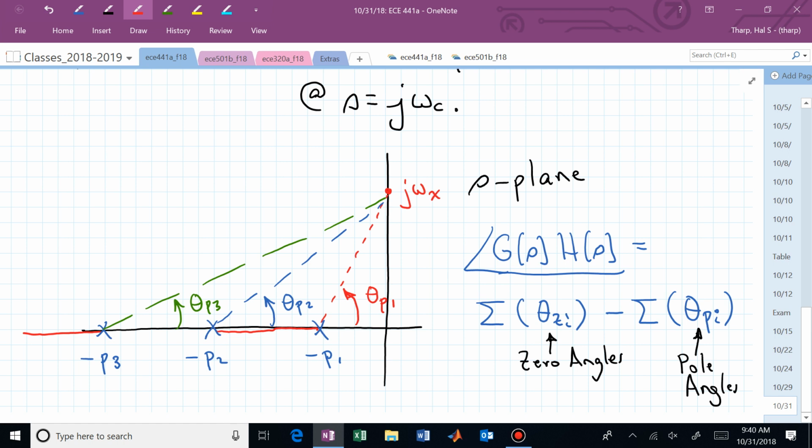We have two branches going at 60 and minus 60, and one branch going off at minus 180. This guy, he's just leaving us alone. He's going off to minus infinity. The other two come together, break away, and approach those plus and minus 60 degree asymptotes. We're now saying, where might that root locus cross the real line? I'm sorry, the imaginary axis.